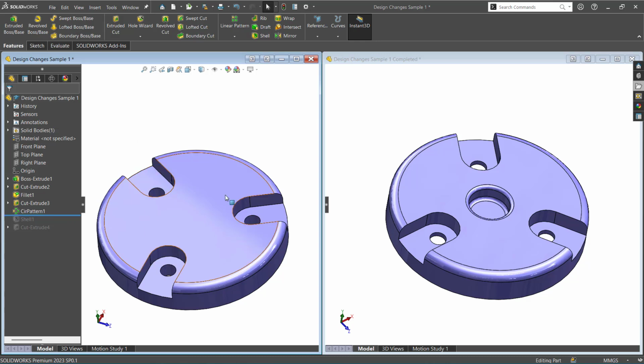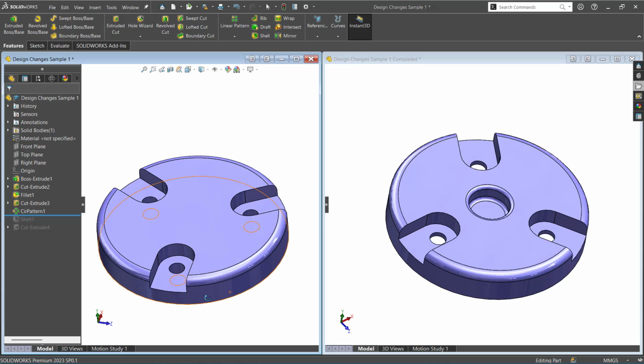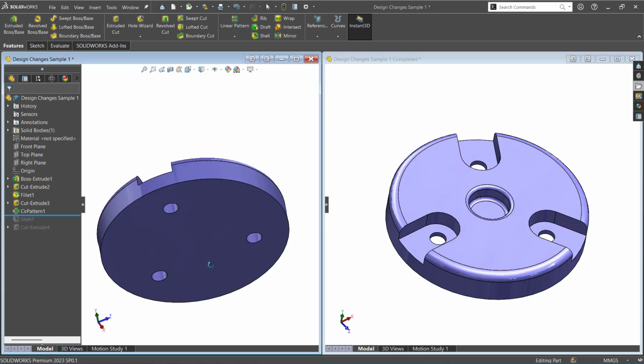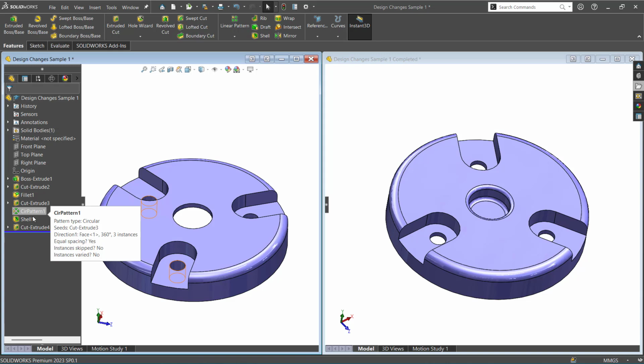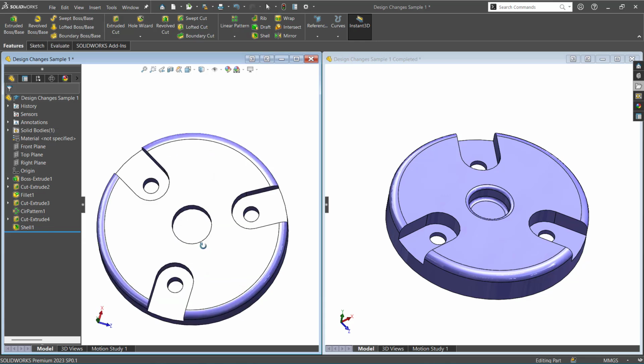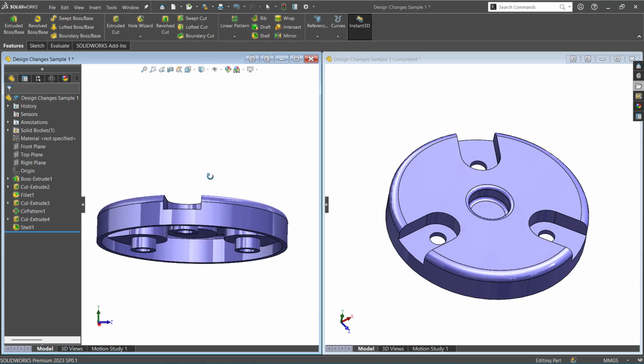Now here it's completely filled, right? If I try to create this one, it is not coming out of this, it is a kind of emboss, right? If I create that, it won't have this hole. Agree? So what we need to do is create this cutout here. Instead of that, I'll simply drag and drop it on the top of the shell. Now you could see that got changed. Instead of a hole we have it.